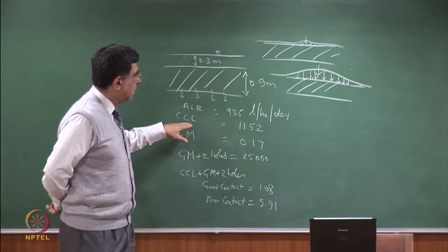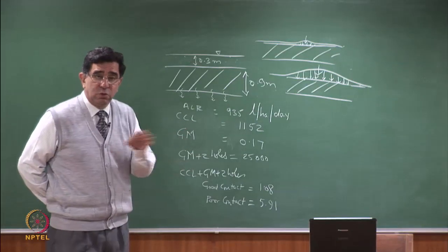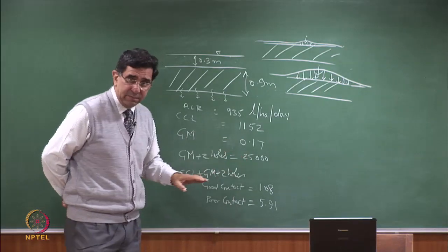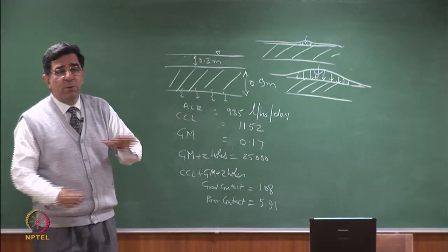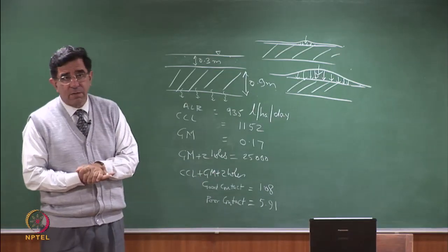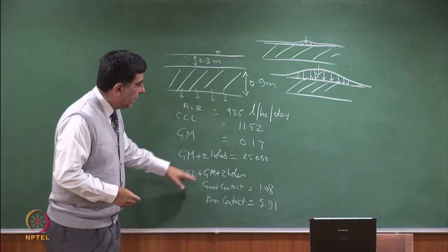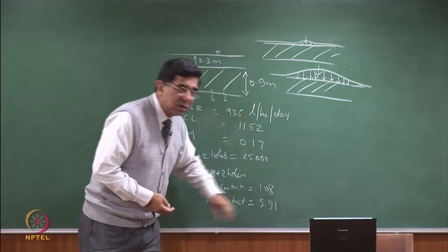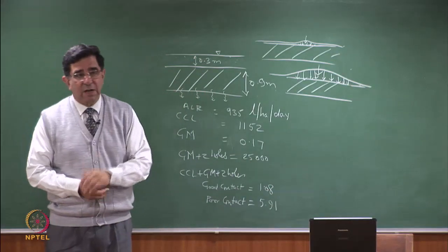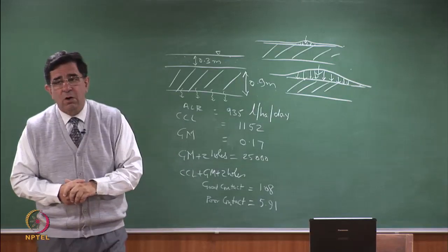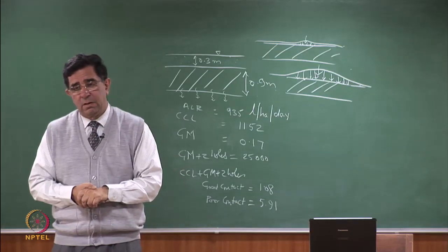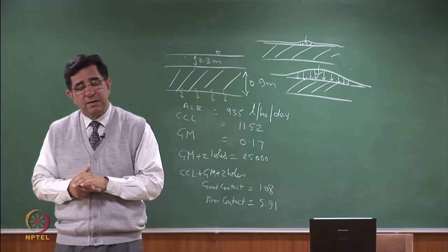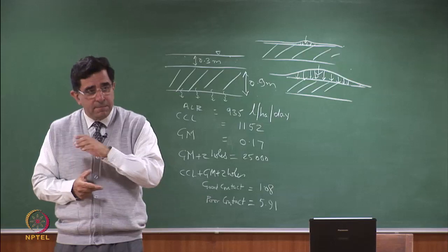If I use a geomembrane alone, it looks very good, but no geomembrane can be laid without a puncture, so a geomembrane with puncture is bad. However, if you put both of them together, even if there is puncture in the geomembrane, the leakage is very, very small. So that is why we use composite geomembrane plus compacted clay liners at the base of a landfill.